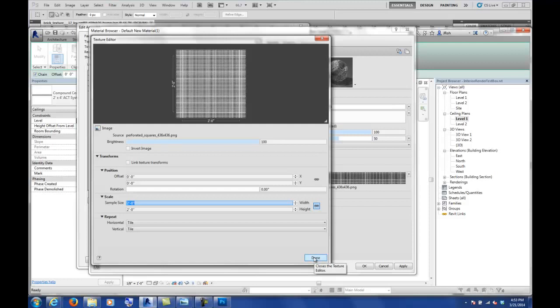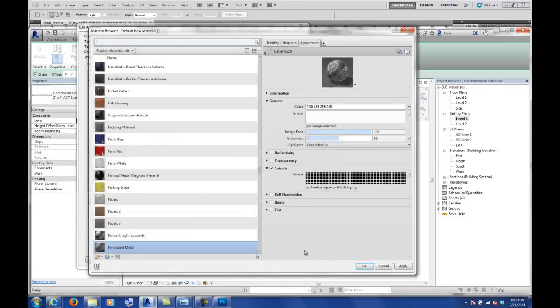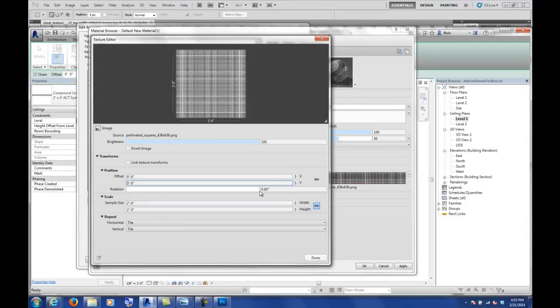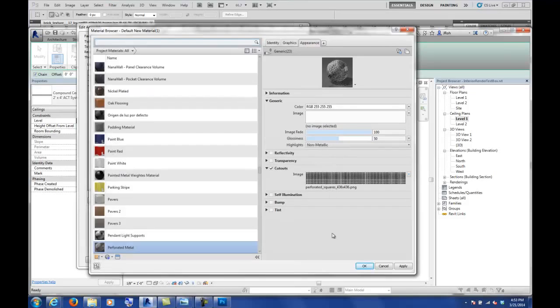And again, that's the overall size of that whole entire image, but that gives me probably a better spacing. Do that again, if you don't mind. Click on the little arrow here and click edit image, and then you might have to scroll down on your dialog box. You have the sample size scale, and you can change that. What'd you change it to? I just did 3 foot square. And then just go ahead and click OK, and that's all we need at the moment.